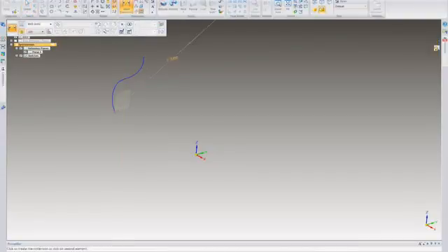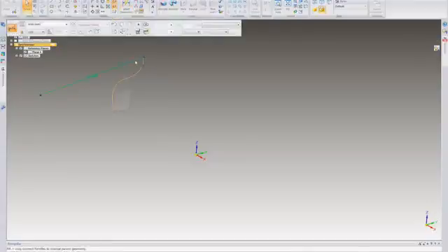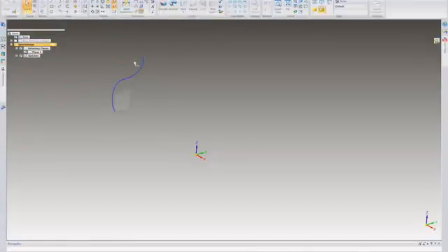All right, so that's really all I can do with the synchronous. Of course, I could always throw some dimensions on here if I really want to start positioning this, but usually with surfaces and curves like that, you kind of want to let them free flow just for the meantime, just to kind of get the shape you want. Then you can kind of go in there and do the final design. You change the dimensions to match what you exactly need.